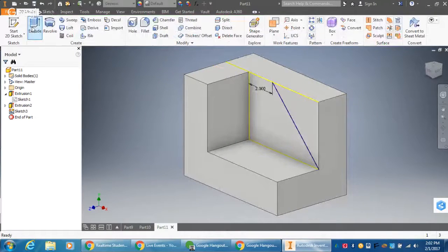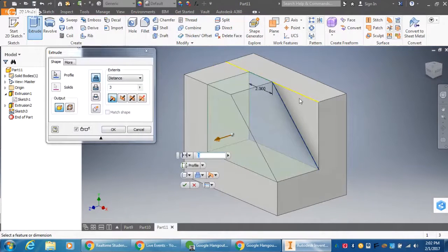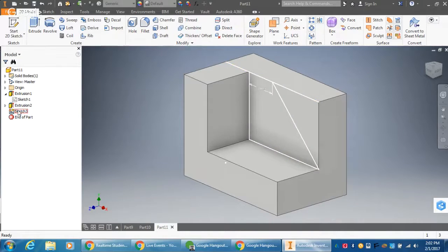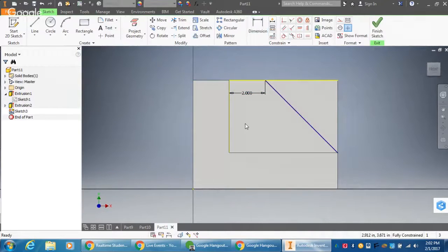We're going to get an error. Oh, look, it wants to extrude that. I don't want to extrude that. I'm going to click Profile. Why can't I click? Oh, no, it's not working. Why is it not working? Well, I'll show you. If you look at all this, this yellow actually turned into a line. So we're going to have to actually make sure that we have closed geometry. We can't extrude a simple shape. So if I have a shape that's like just a V here, those are just 2 lines. That's not closed geometry. I get my green dot. Now it's closed geometry. Now I can do something with it.